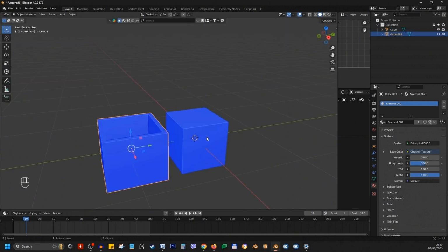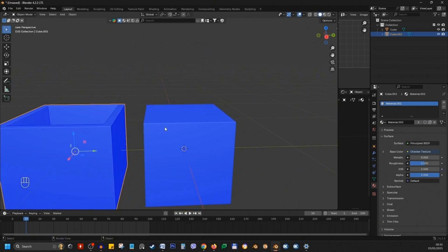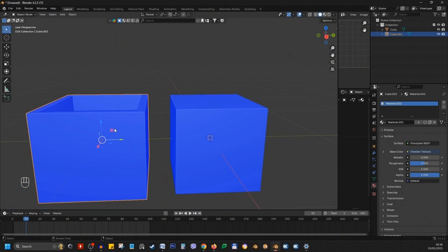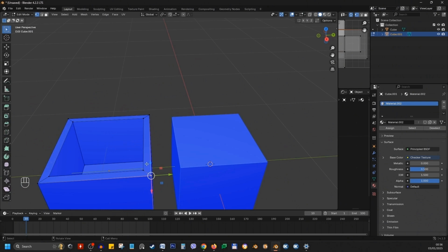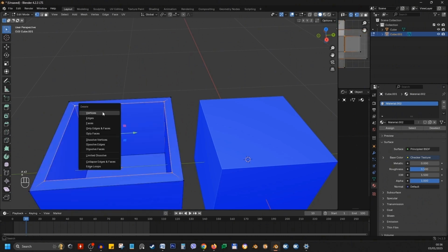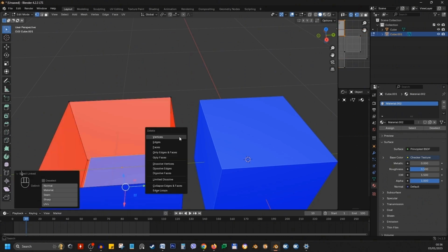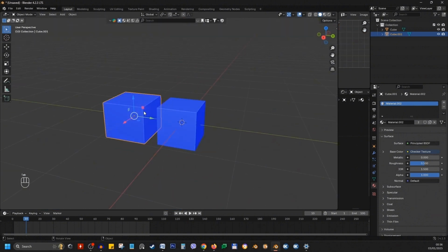There are different ways of adjusting geometry of each object in Blender, and there's a clear distinction between destructive and non-destructive modeling. What this means is, for example, the changes that we made to this cube are destructive, meaning we destroyed its original shape and created something different. This is not a huge problem for an object like this, because I can just delete this, delete that, add in another face there, and now we have our original cube.